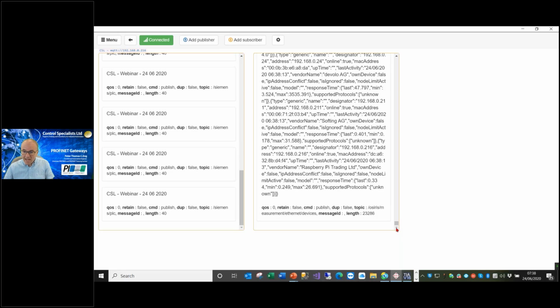What I've found is that this is very dependent on the capabilities of your PLC, the size of your program, etc. So be very, very careful before you commit. In reality, I would think that the information on the right is probably more akin to being put into a database rather than some PLC, because this is a large amount of data and I couldn't read it into my PLC at all. I had to limit the amount before I could get it to work.